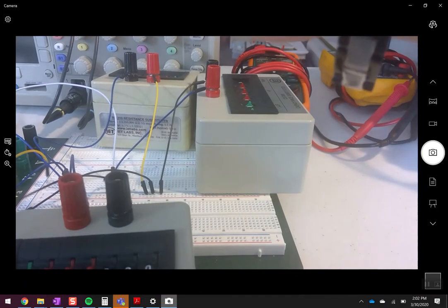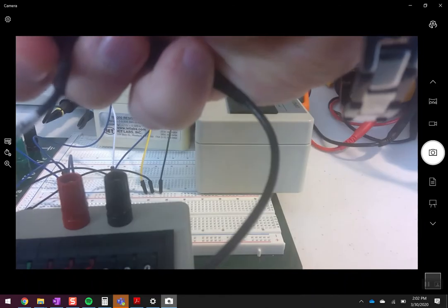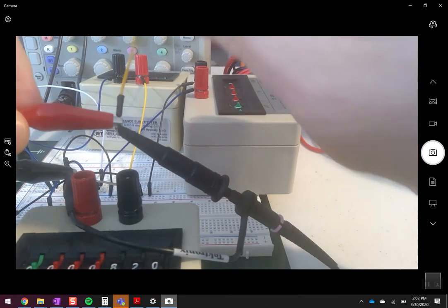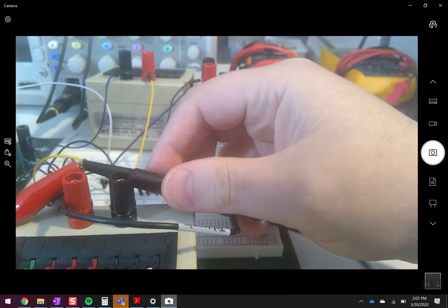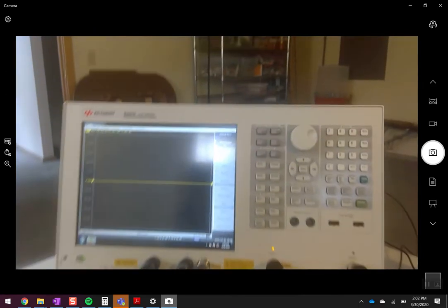I've got to fix it up here. I've got both the signal in and the measurement probe connected to the input, which would be on the input of the 820 ohm resistor. So now I'm going to come over here to my network analyzer. It doesn't look like it's in the right state here, but once we've got it all configured once, and you don't change the probes, you don't have to constantly reconfigure it.